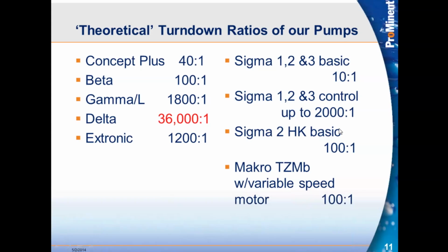Why is minimum strokes per minute limited to 30% of maximum? It's not the stroke speed, the frequency, strokes per minute, that's limited to 30%. It is the stroke length. That's what we're suggesting to be the minimum. It's not physically limited. You can actually turn it down further.